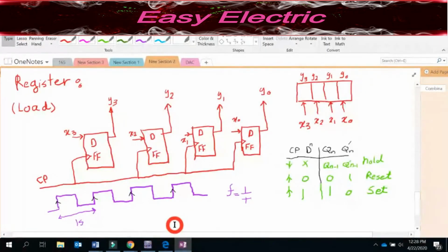Yeah, 10 seconds. So see what I did, I actually put 0.1 equal to 1 over t, right? So this is 1 over 10, which means t is 10 seconds. So right now, from here to here is 10 seconds. So if I give 1, it's actually on, and whenever I immediately turn it off, it should still be on for 10 seconds. After 10 seconds, whenever it sees the second rising edge, it updates the value, right?